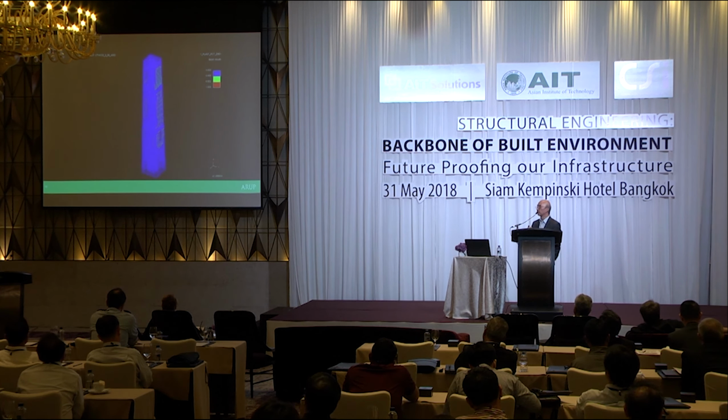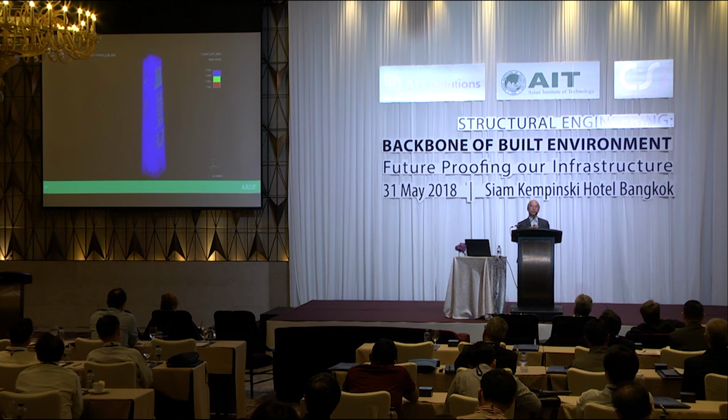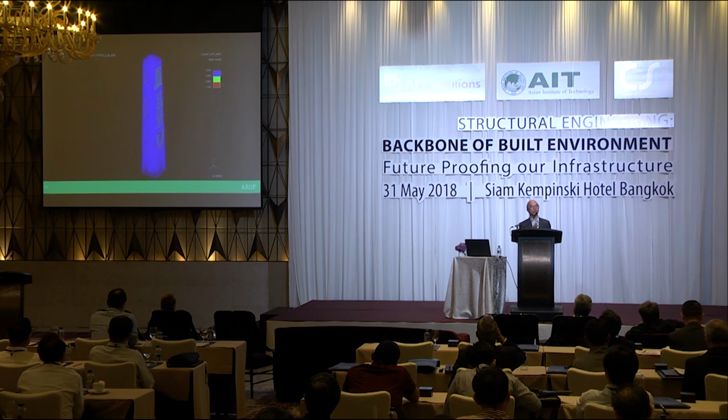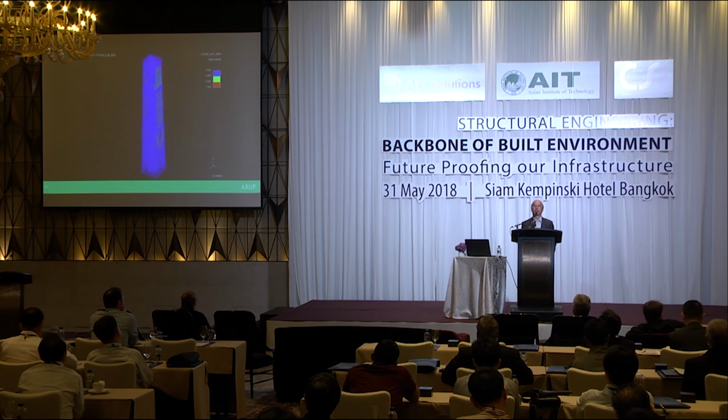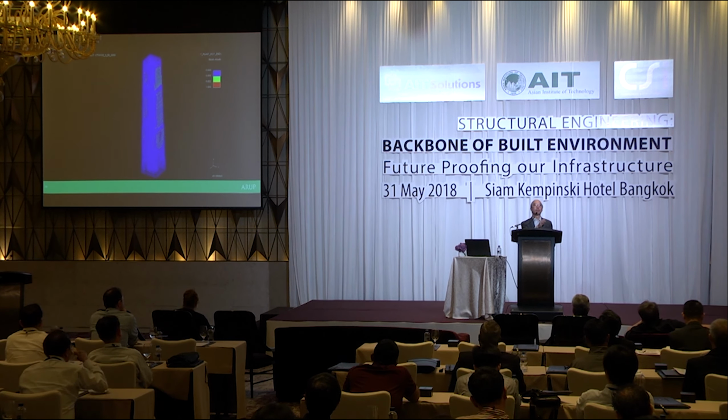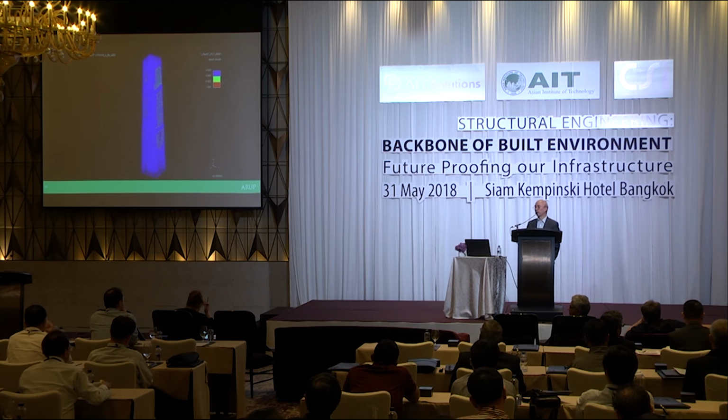We can check which member yields first, and how load is redistributed, and so forth. If you want to change the behavior, we can look at this result to do so. Basically, the nonlinear time history is used to validate the performance of the building we have designed, whether it can meet the 2,500-year earthquake event.